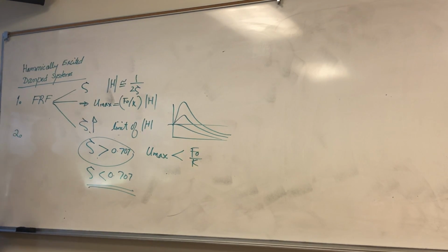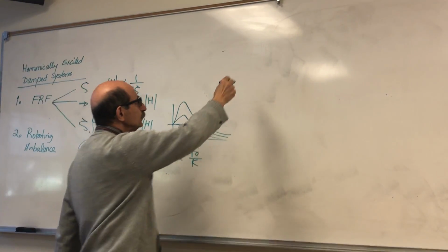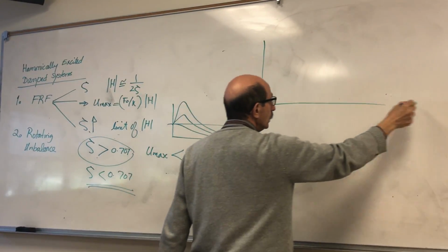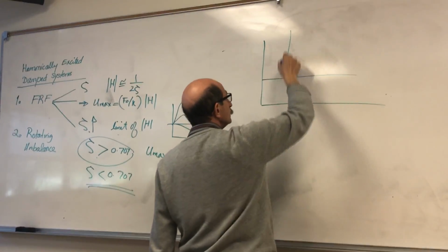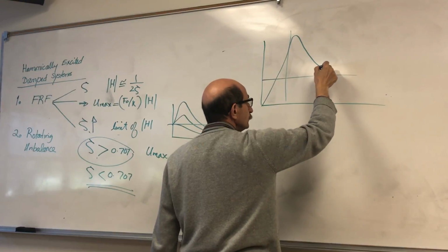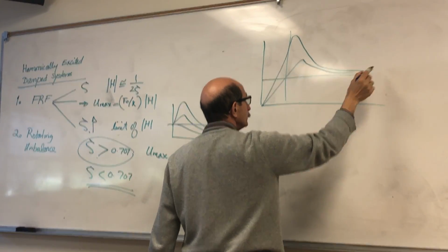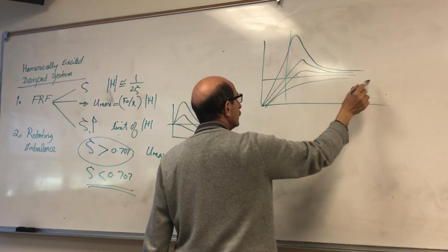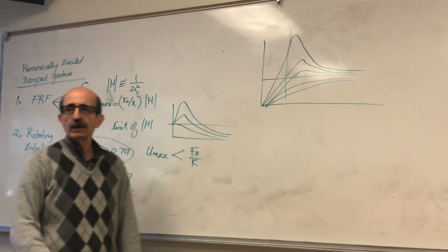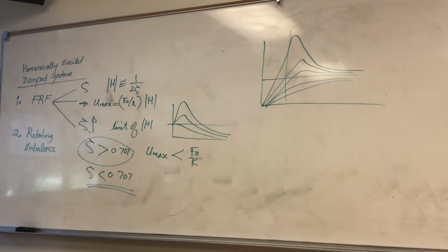The second topic we looked at was a special case of a harmonically excited system, and that was rotating unbalance. In the case of rotating unbalance, we derived the equation of motion, and we defined the pseudo frequency response function, and we saw that no matter what the damping ratio is in the system, the response will never go to 0.